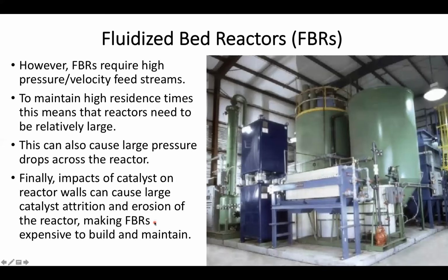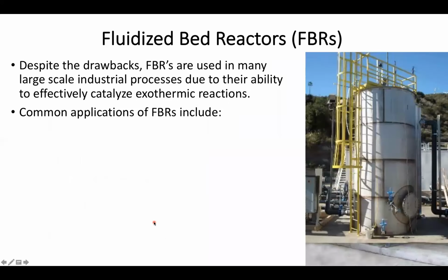So this means that our fluidized bed reactors tend to be almost the most expensive to build and maintain, but it turns out that they're usually worth it for that high rate of conversion and their ability to deal with highly exothermic reactions. Because if I tried to run this same process in, say, a packed bed reactor, I'd end up with a hot spot that may either end up killing my catalyst or overcooking my materials.